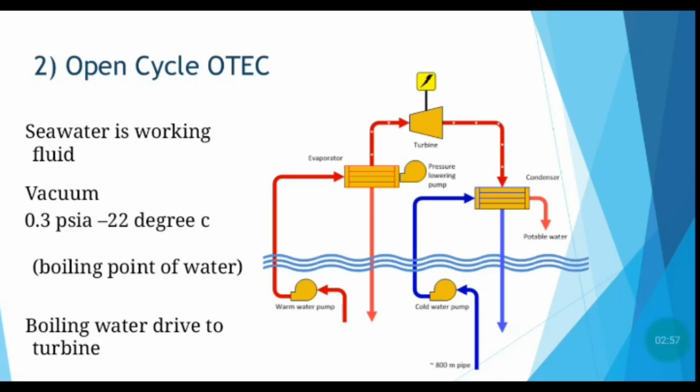The open cycle consists of flash evaporation of a fraction of the warm seawater by reduction of pressure below the saturation value corresponding to its temperature, the expansion of the vapor through a turbine to generate power, and the compression of non-condensable gases from the seawater streams at the low operating pressure to pressures required to discharge them from the system.